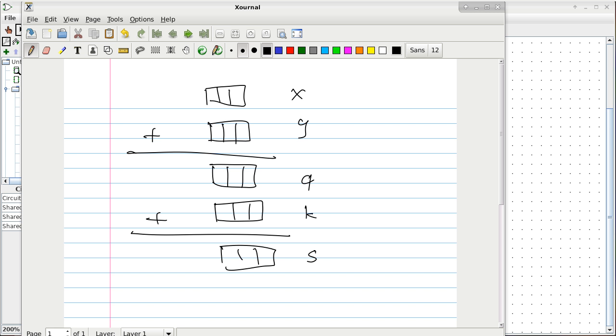Well, we can also have a carry because we are adding this one and it has a carry here, right? But how can that happen? Well, K0 has to be a 1. It's an input pin. It can be 1. But this one also has to be a 1. But how can you make Q a 1? The only way to make Q a 1 is X is a 1 and Y is a 0, or X is a 0 and Y is a 1. So in all of those cases, you have at least 2 out of these 3 bits being a 1 in order to end up with a 1 here.